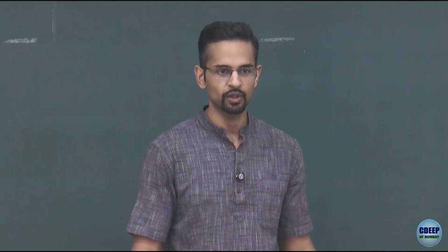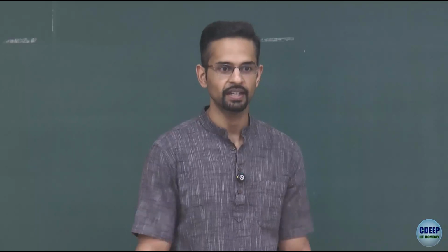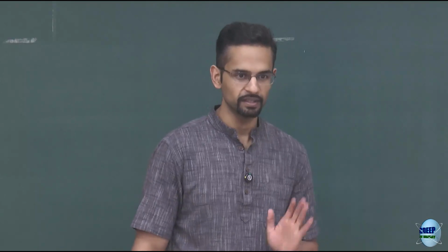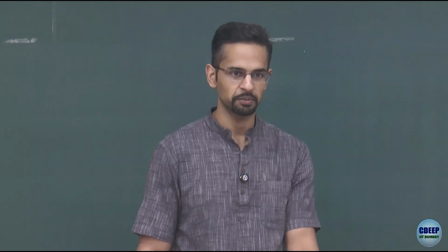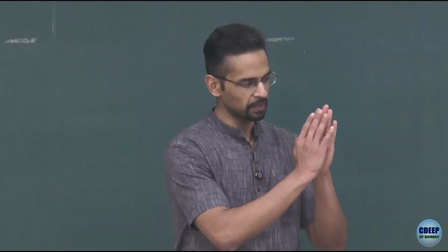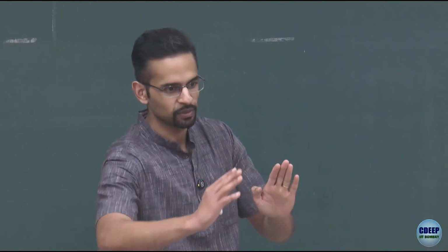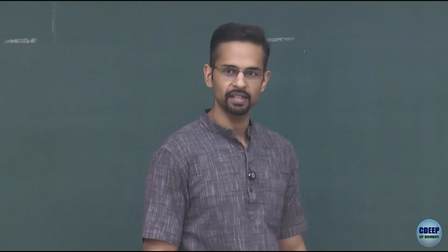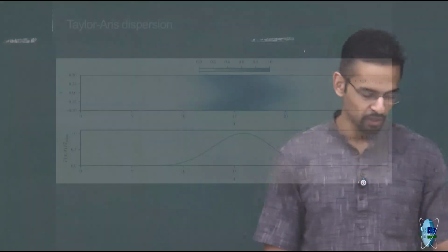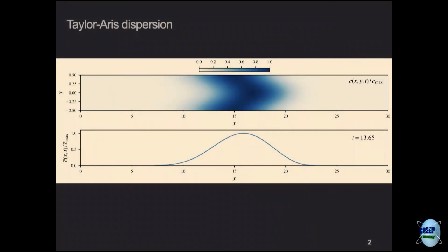And this looks like the solution of some 1D diffusion equation, because if I have a 1D equation, advection in x at some uniform speed, and diffusion in x, I would get this result, right? I would take a pulse, the pulse would move at some speed while it diffuses. It's like standard 1D advection diffusion. So the remarkable thing is you have got something like 1D advection diffusion from what is a 2D problem with advection which varies in the r direction.